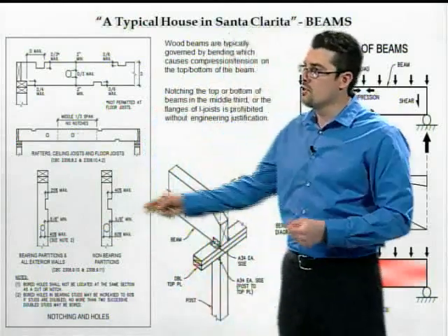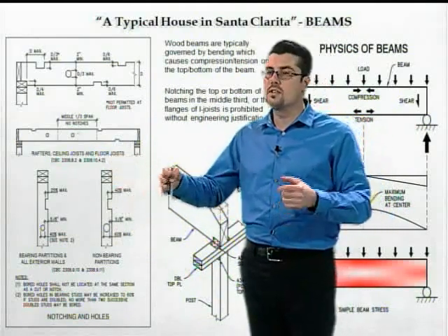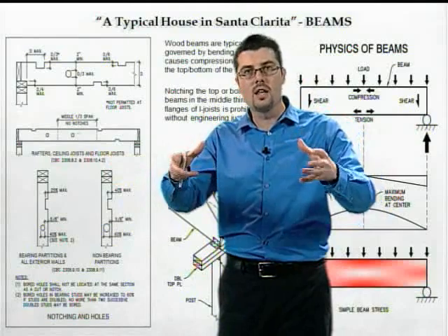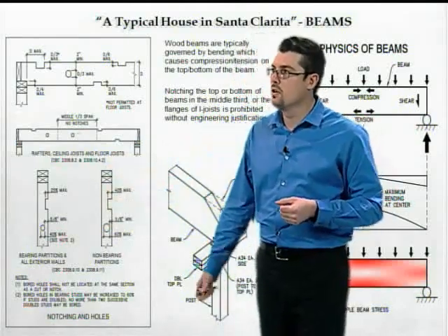Same thing for studs, essentially. You'll notice for studs, concepts are pretty much the same. Studs aren't acting like beams, so they don't have a lot of bending, but there are still limitations on how much you can bore into studs.